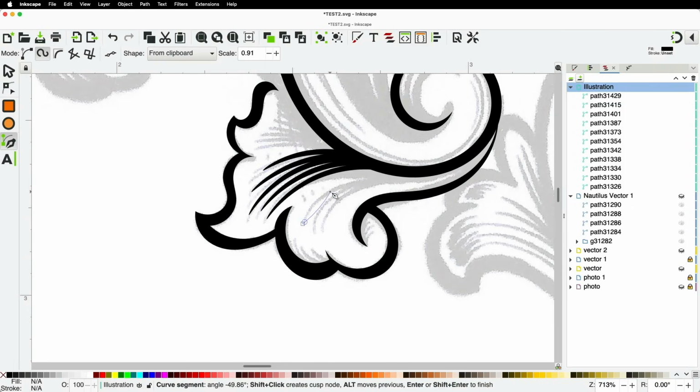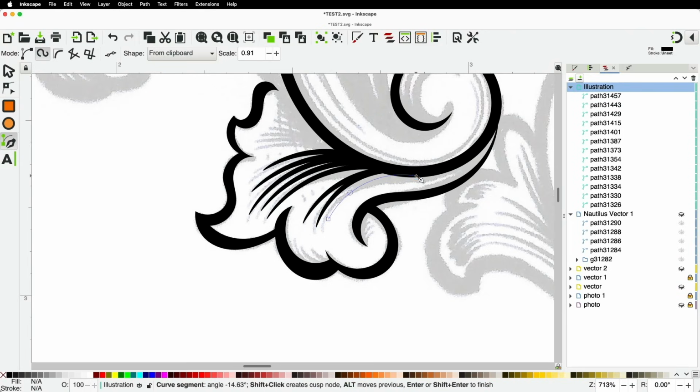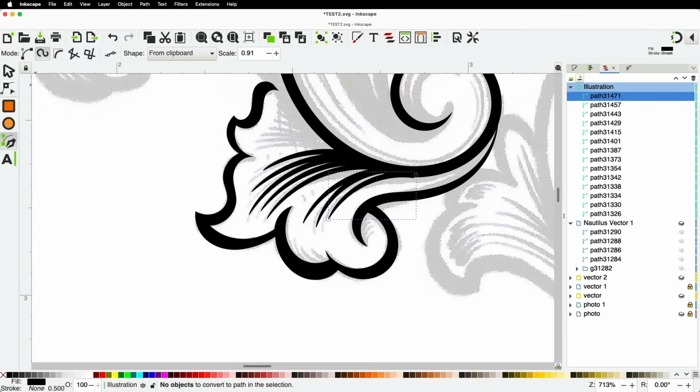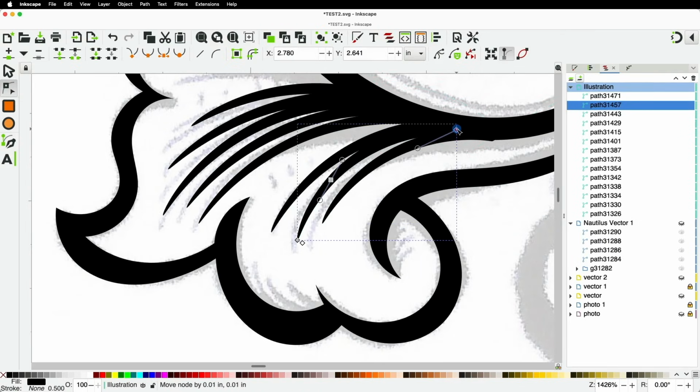Oops, there I have actually 3 points there. So I'm going to hit the Control Z to back out, hit the Control Z again. Sometimes when you place a point, you may accidentally double click it and it will create 2 points. These, like all the other elements, are very easy to edit. Just go back up and select your nodes and you can make it perfect.